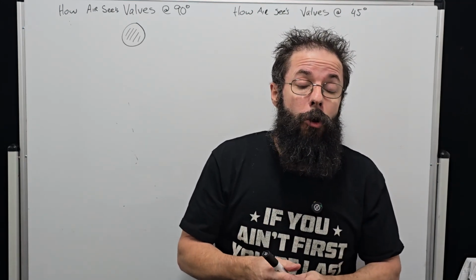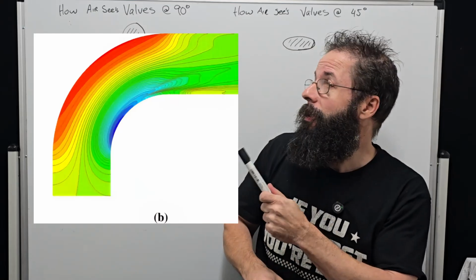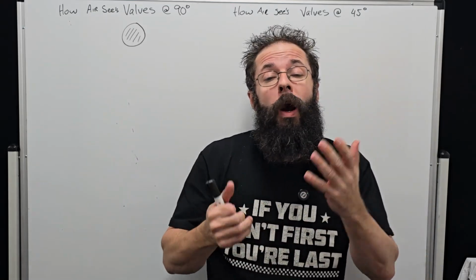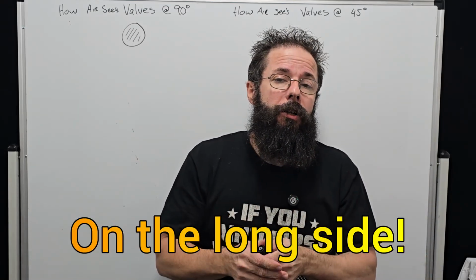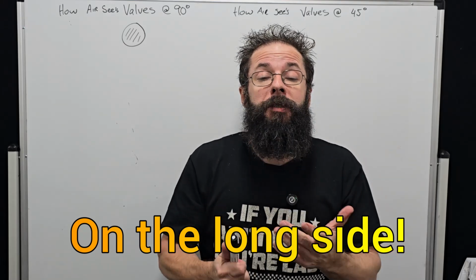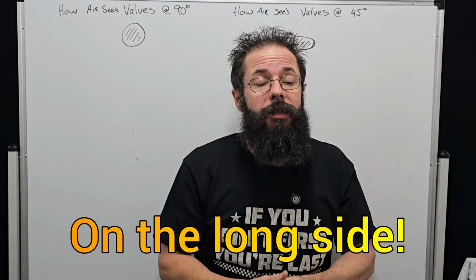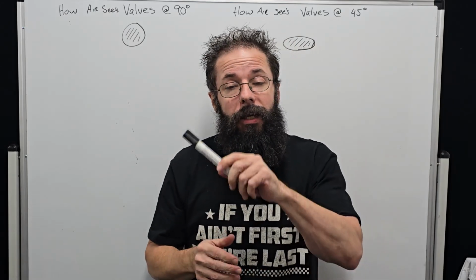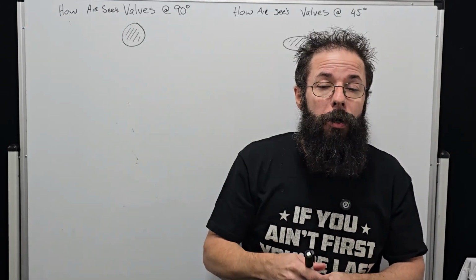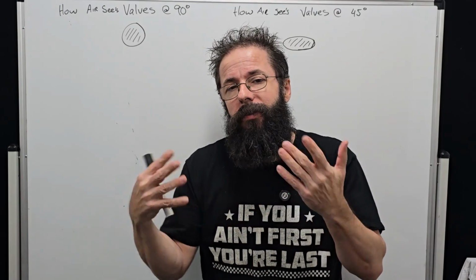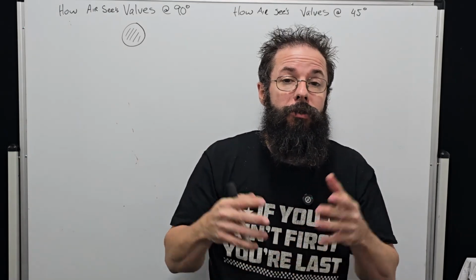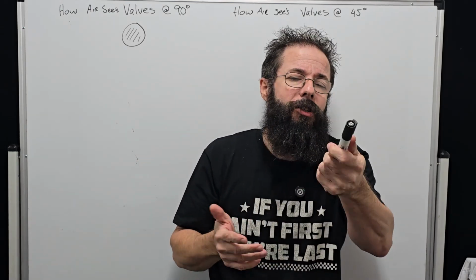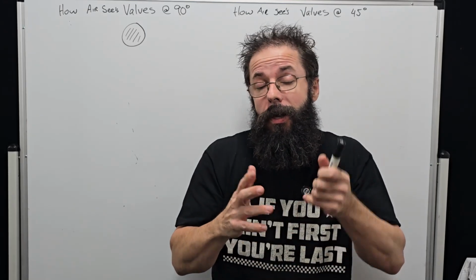pressure gradients. So as you can see by this diagram, where all the pressure is on the 90-degree bend, this is why optimally mandrel bend isn't the best for turning a corner. And again, you can see by the pressure gradient in the corner, this is why I say we need to look at both the velocity gradients and the pressure gradients to understand what's actually happening. And this should really be common sense.